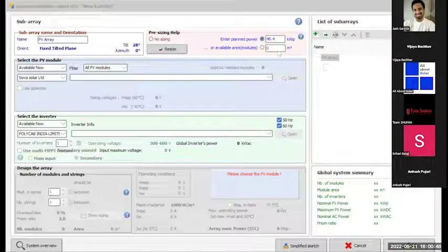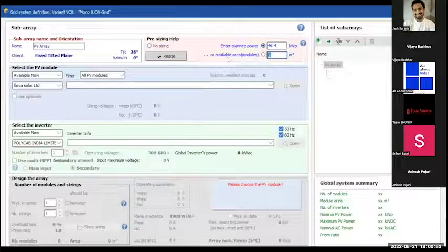But during the installation of solar modules, you need not only the module area, because when you are giving an angle to the solar module, there must be a certain gap you have to maintain between each module. So it's not like only modules will be there. There will be a certain external gap also involved. That's why this part is always neglected. You should not consider this thing.